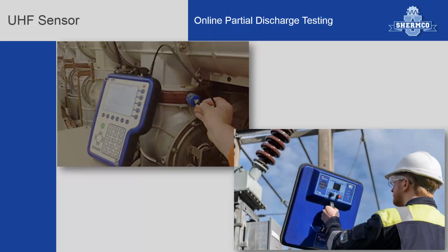To prove that the UHF that we're picking up could be from a partial discharge activity, we can show that there is a 180-degree separation, 8.33 milliseconds, between the UHF pulses that we're picking up at the sensor feeding into the partial discharge receiver. This is a function of time resolved or phase resolved measurements. The phase resolved measurements are made in real time and serve as a basis for very quick PD detection assessment in the field.